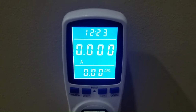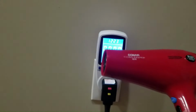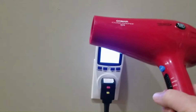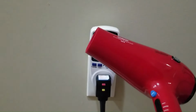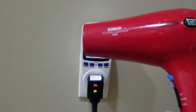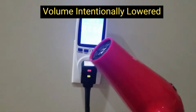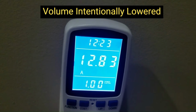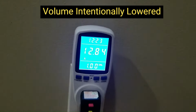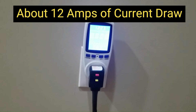So we've got a form of a kilowatt meter here. I'm going to test the current draw of this hair dryer. We're going to use that current draw to determine how much voltage drop should occur at this outlet. So I'm going to turn this hair dryer on. So we've got about a 12 or so amp draw in this hair dryer.